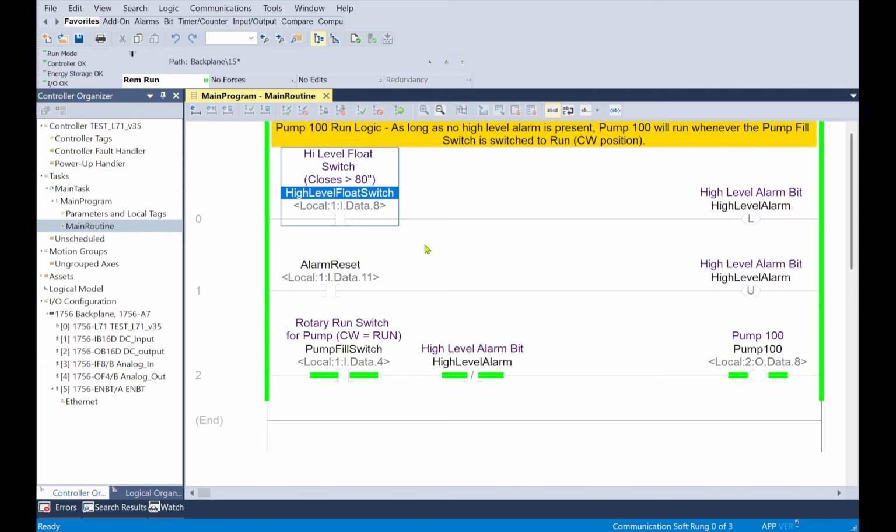So I've got some logic right now connected to a PLC. This is just some logic I was using in a previous blog, and I just pulled it up. Wanted something small and simple to see. If I'm looking at this logic, when the high level float switch goes high, notice the power flow, these green lines on the rails. They tell you that the logic is scanning. It says, yeah, this logic's active, which is a great clue.